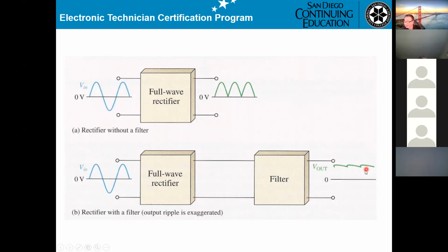If you're looking at the output DC here, riding on AC, they get a ripple. What is it? DC riding on AC. Sawtooth. My question is, when you're looking at the output here, you see what they call a ripple. What is it? The capacitor fill in. Now, the half of the sinusoid that you are feeding, basically. It's sawtooth, right? That is the noise.